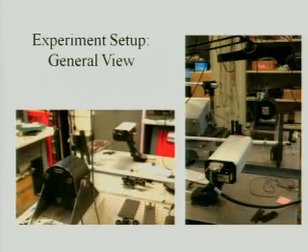Let's take a look at the experiment setup. The black one is a shaker table. You see it has a little aluminum block in the front of it. It's a dummy test platform. We are not going to use it for our real measurement. And the shaker is shaking back and forth. The white one is a laser vibrometer. It shoots a laser on the block and reflects it back, and sends the signal to the controller. The controller will give an output signal. You see the little bar here. This indicates the reflected signal is pretty strong.